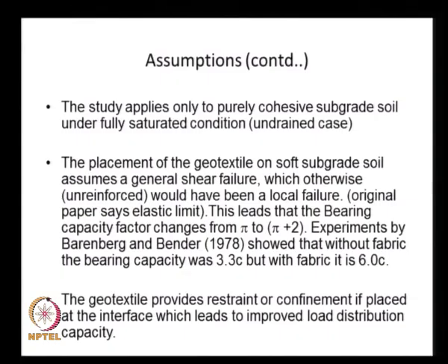And the main assumption is that because of the provision of the reinforcement, we can increase the bearing capacity factor from pi, that is 3.14, to 2 plus pi, that is 5.14. That is based on laboratory and field observations by Barenberg and Bender, published way back in 1978.